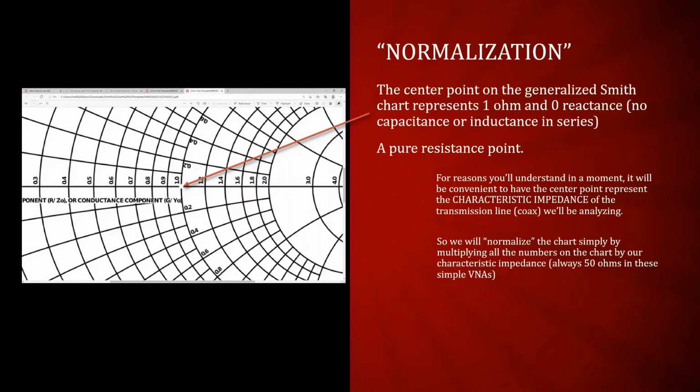Your VNA does this automatically. The big boy machines can have different numbers, but your VNA only works with 50 ohm systems. Yeah, that's the price you pay. You want to do some 70 ohm work, pay the 50 grand, and you got it. So moving on here again.